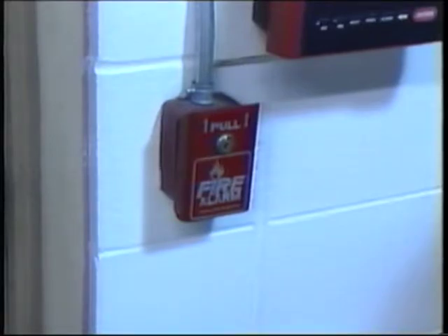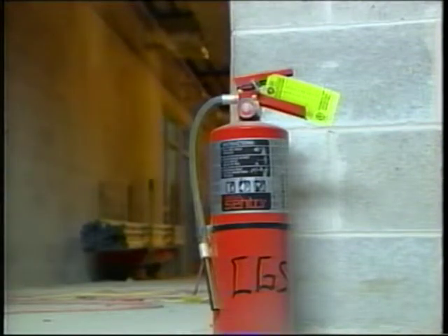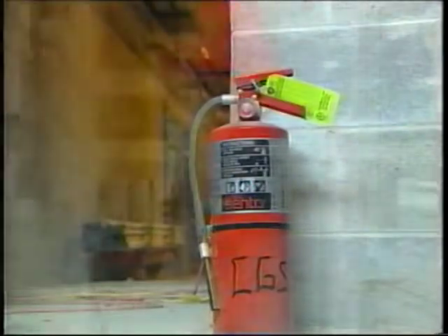Someday it could happen. There could be a fire, and you might be the first one to see it. Will you know what to do? At your job site, there's a firefighting program that's been prepared for all phases of construction and demolition work. Be ready ahead of time for your part of the program by knowing where alarms are and when to use them, and where fire extinguishers are located and how to use them. It's important to remember that fire consumes oxygen as it burns. In fact, more people die from lack of oxygen than they do from burns. So move quickly, but don't panic.